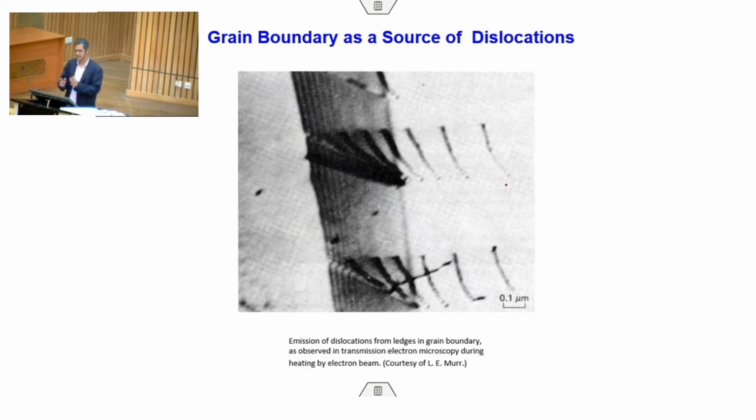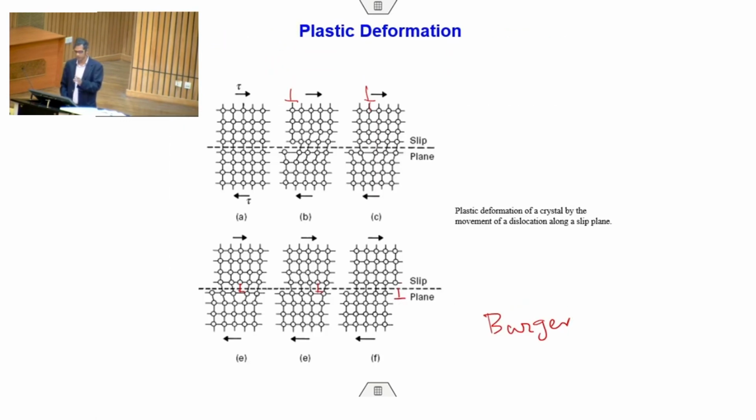So, a dislocation generated from the grain boundary slowly moves inside the grain. You can see one by one, dislocations are moving inside the grain. There is a distance maintained between two dislocations. This distance must be maintained because there is a stress field associated with dislocations. There is an extra row of atoms, and this portion is bent. You can clearly see atoms are bent here, extended here. Because of this nature, there will be a lot of strain.